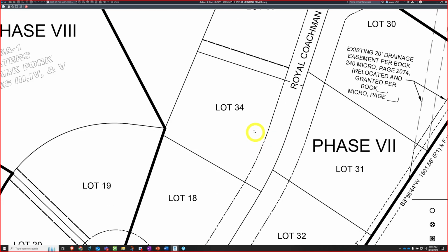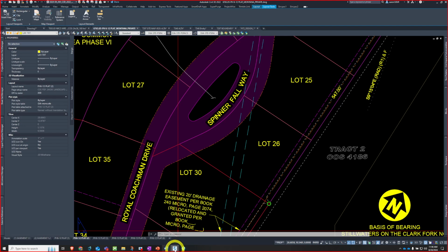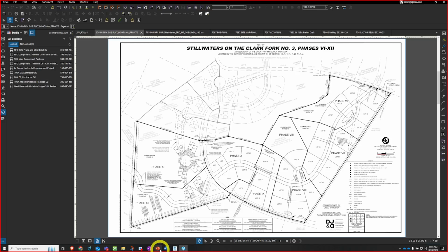I use wipeouts a lot when I have tough situations. You could use layer control, wipeouts with overlapping viewports. Sometimes I've got to use some wipeout trickery. I had to use it a lot on these MDT right-of-way plans at match lines, where there are some things I don't want to show from sheet to sheet. But anyway. Okay, thanks. That's new to me.